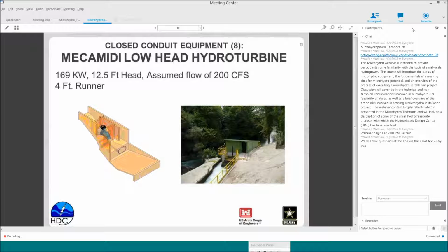So these next couple examples are units where we have crossed that 100 kilowatt threshold into the mini hydropower range. Now, as we start to move into that slightly larger range, you'll notice that the construction, the footprint of these, that initial investment cost has gone up as we've crossed that threshold from simply install on a pipe to perhaps something that is going to require something more like a powerhouse here.